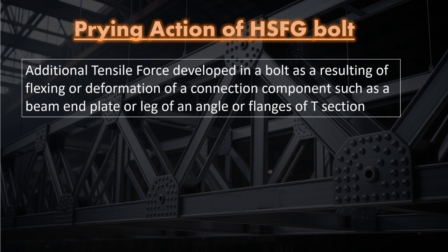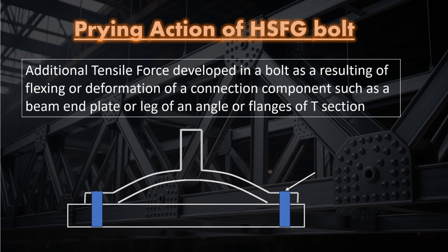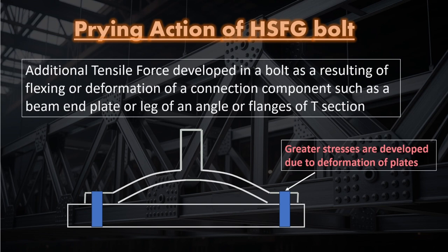Prying action of HSFG bolt. Additional tensile force developed in a bolt as a result of flexing or deformation of a connection component, such as a beam end plate or leg of an angle or flanges of T-section. Greater stresses are developed due to deformation of plates.